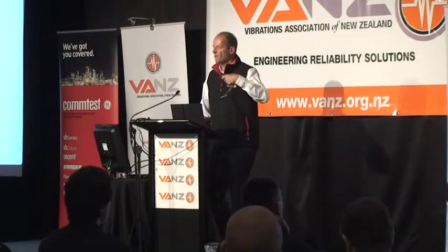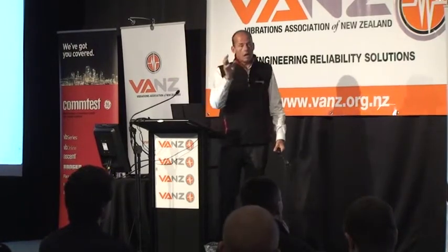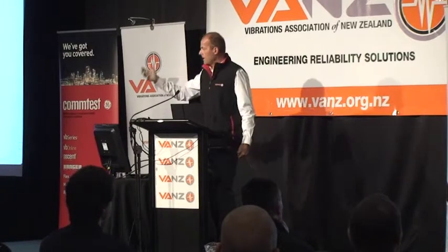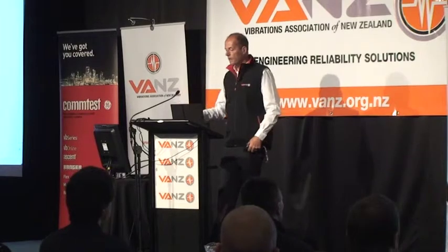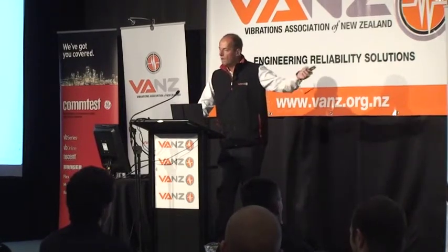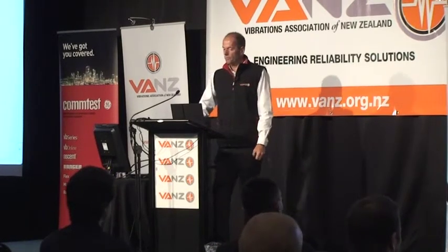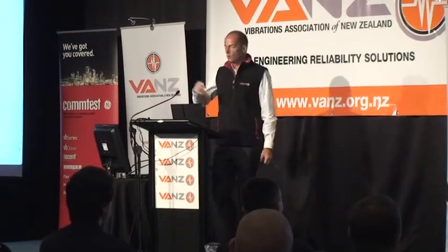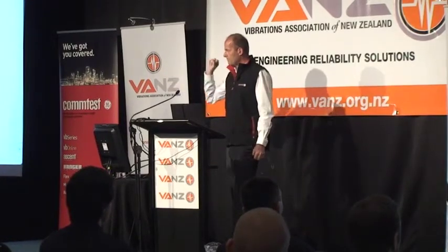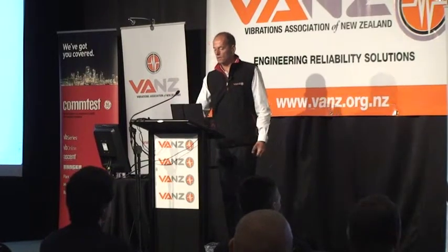Now I say unreliable suppliers. I don't mean suppliers that don't deliver on time. I mean suppliers who, unbeknownst to you, sell you bearings or motors or pumps or whatever else that already are defective or they're not properly rated or whatever. We've got cheap spares that don't do the job. It's not being transported properly, or we've got contractors doing balance jobs or rewind jobs or whatever, and they're not doing a good job for you, and you don't know. You're not specifying how it should be done. You're not specifying what a good job means, and you're not testing it with acceptance testing when it comes in.